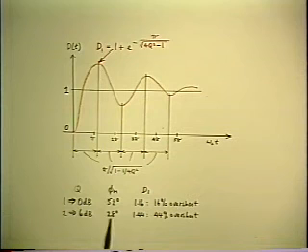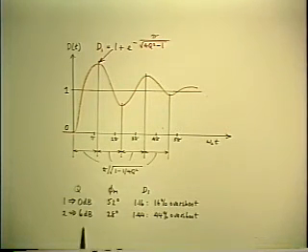Compare that with the worst case where the phase margin is only 28 degrees with a Q of 6 dB, and that gives you 44% overshoot. Again, probably not acceptable, just as the frequency response peak of 6 dB probably wouldn't be acceptable either.